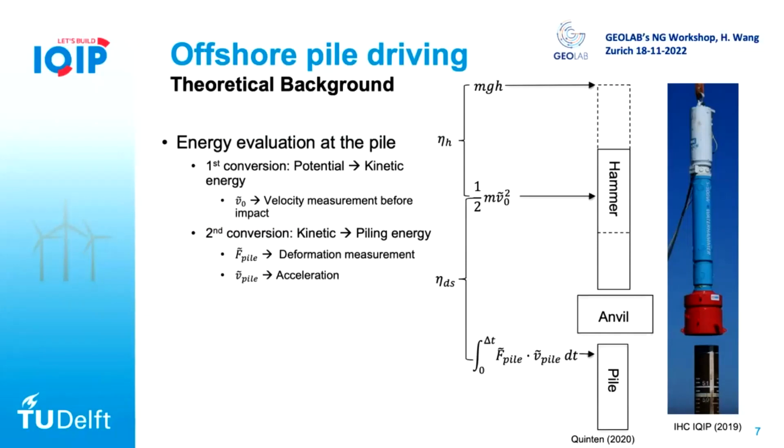And between the anvil and the pile, there is also some energy loss. So there is something we can do to improve this whole process. For example, back to this hammer of a nail, I think in our daily life, I don't know if you have the experience, if you hammer the nail in something very stiff, there is some bouncing back, and sometimes you just put a very soft material in between, then you hammer again, and it can penetrate easily. So this kind of idea can also be used to optimize the hammer system.